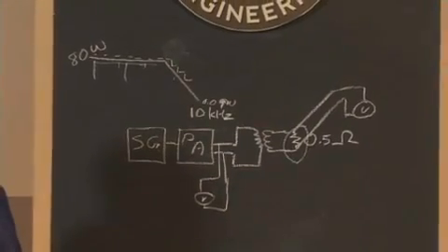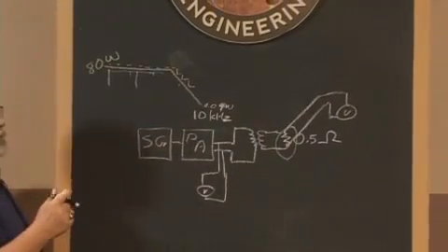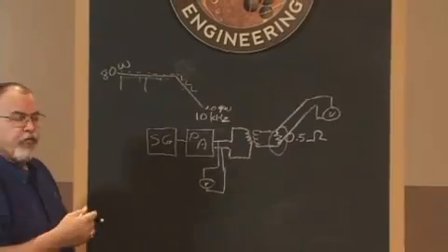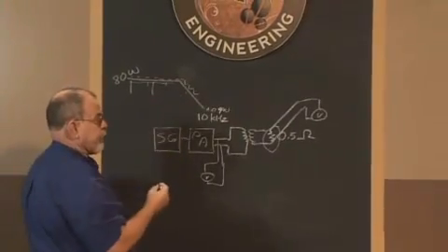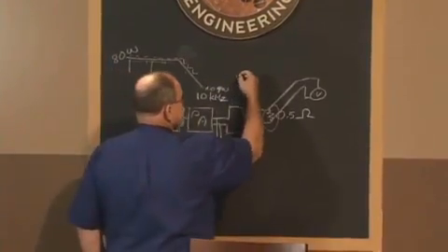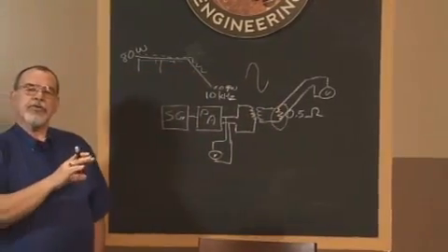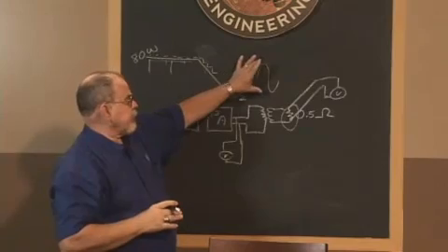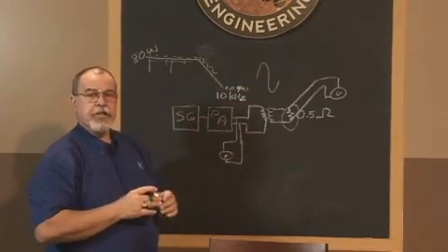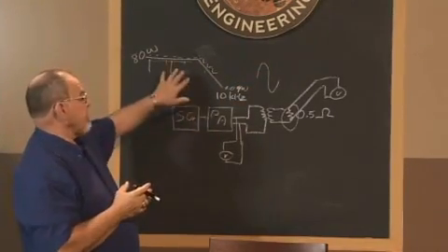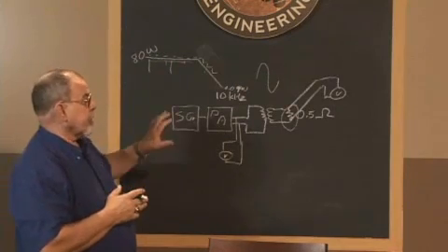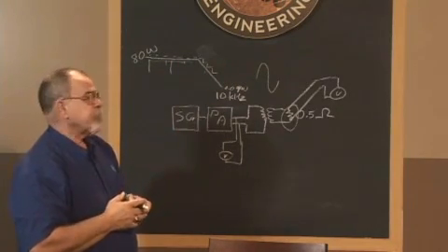They just want to measure the points. The idea is we need to verify that this waveform that we're planning to do interference testing with is sinusoidal in nature. So we'll be monitoring this. We'll also, during the process, look to see if there are fluctuations that cause this thing to decrease or increase, and we'll adjust the forward power to where we're producing the right levels.